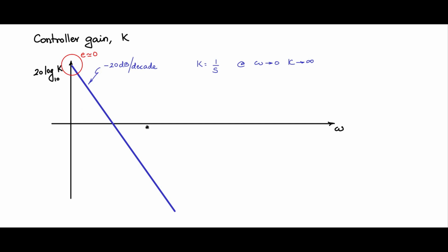Now as the system moves towards higher frequency zones during different points in the operating region, you would like to have the gain K lesser and lesser as the frequency goes higher. The reason being, as I told before, the noise is larger as you start going towards high frequency, and therefore you have to reduce, attenuate the gain if you want to get meaningful control signals. Now this is just plain I control. You just have 1 by s integral, and that is I control.